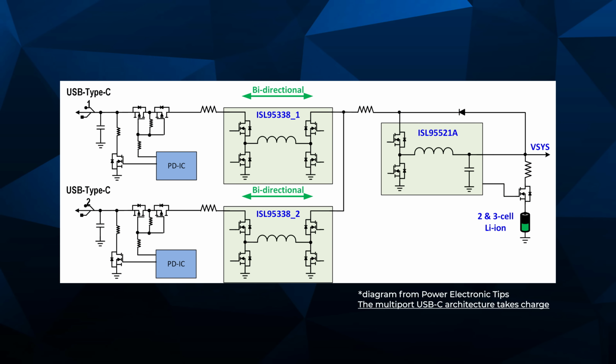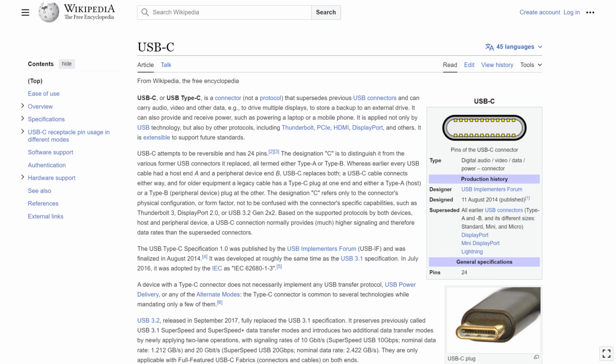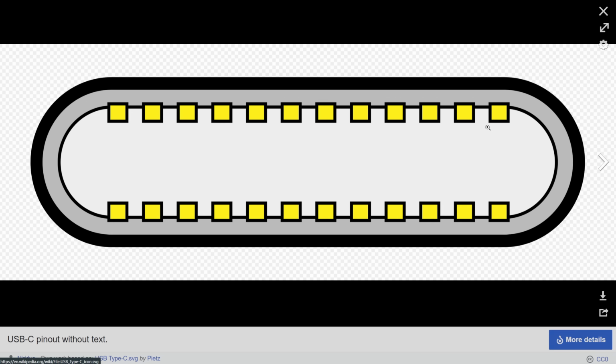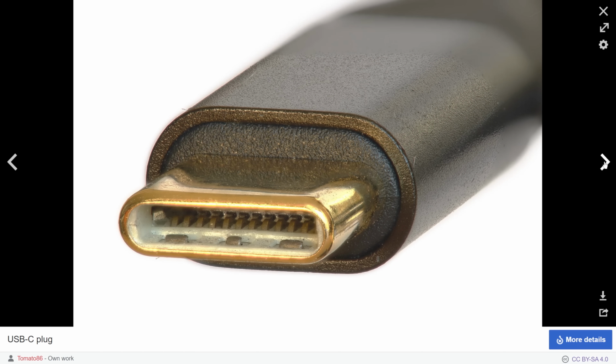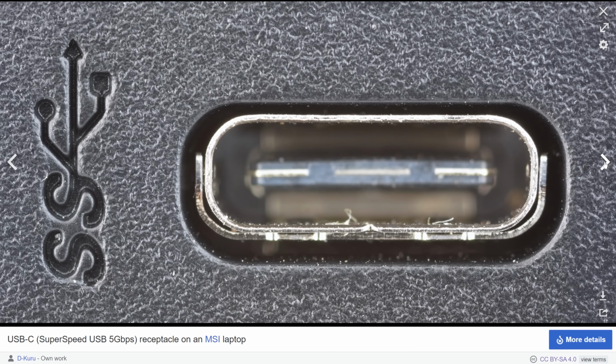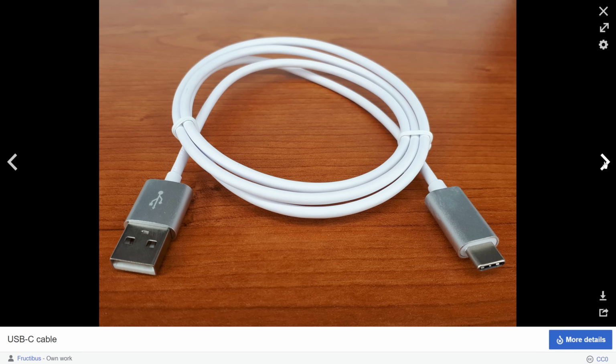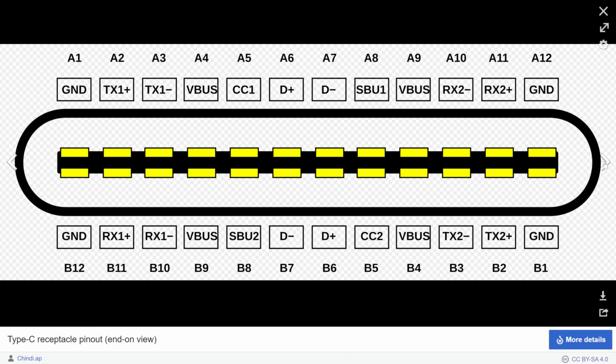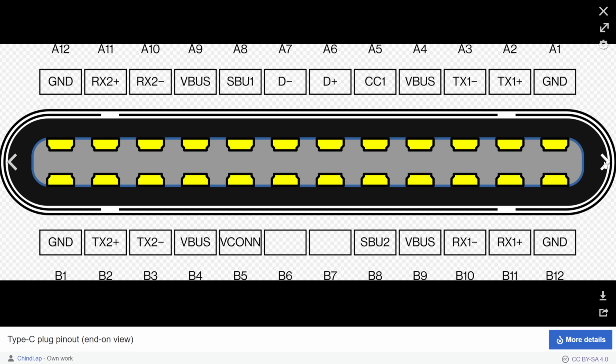You see, that type of a layout with that many wires in your cable and that much going on in a tiny little USB-C connector generates a lot of RF interference. Not just for other devices, but even for other radios that exist in your device. So if you wanted to have an 8-lane Thunderbolt setup, for example, that would run at 80 gigabit instead of 40 gigabit. It's the equivalent of 8 PCIe lanes because there really are 8 channels on the wire, as there are 4 channels with Thunderbolt 3 and Thunderbolt 4 on the wire. Well, 4 channels plus there's a lower bandwidth side channel, but let's not be super pedantic.